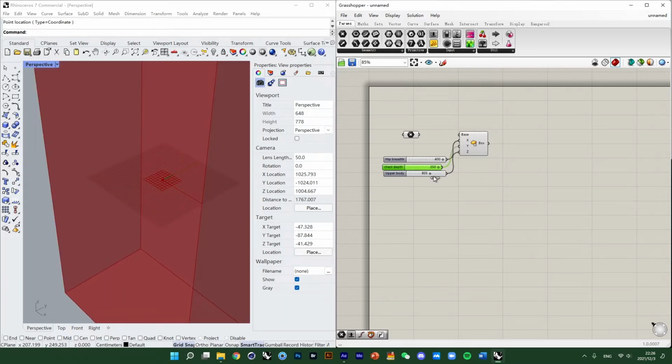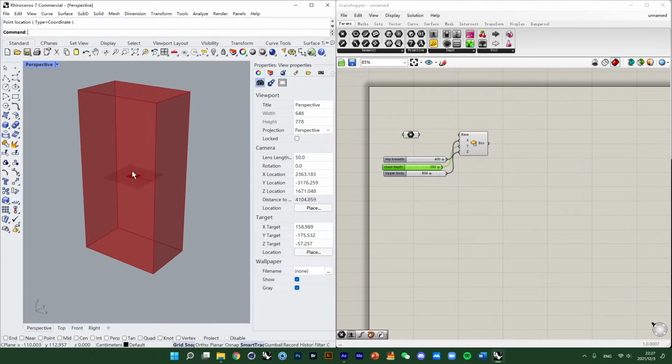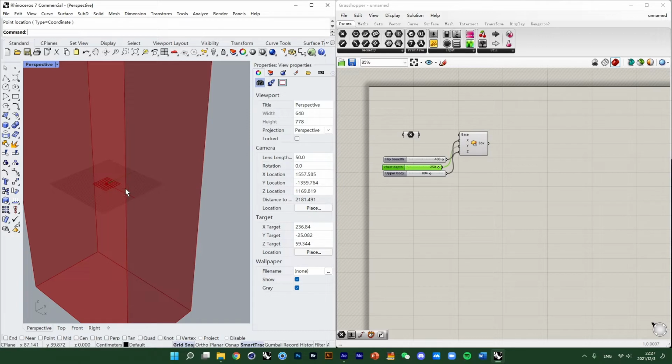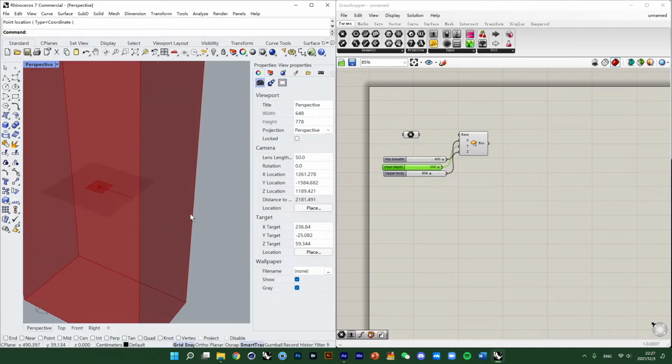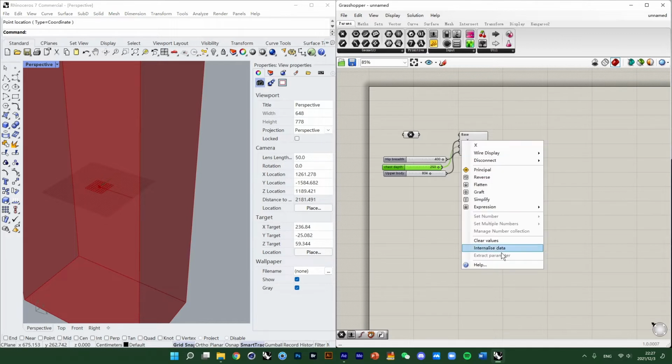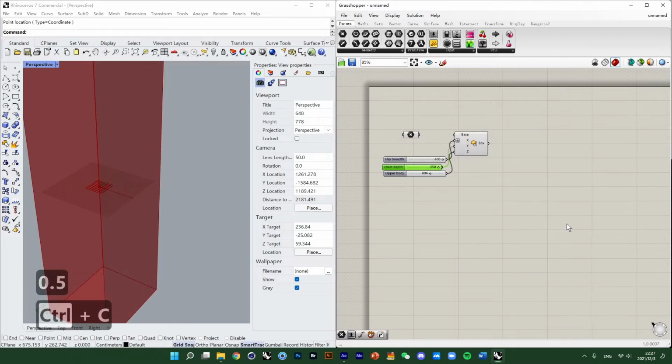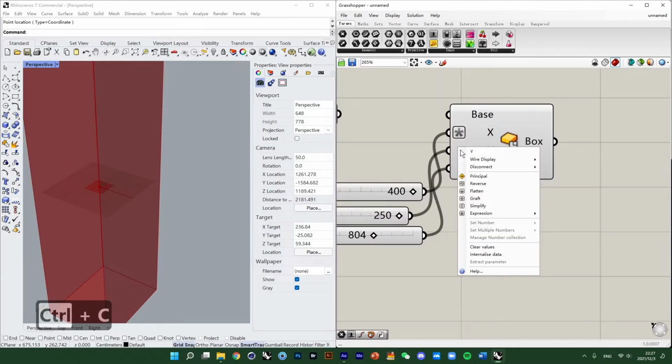And here's a small setting. When we build our center box, the distance is actually calculated from the center to the edge. So what width we need is actually half of the input. So we can set an expression here, set half of the value, and get what we want.